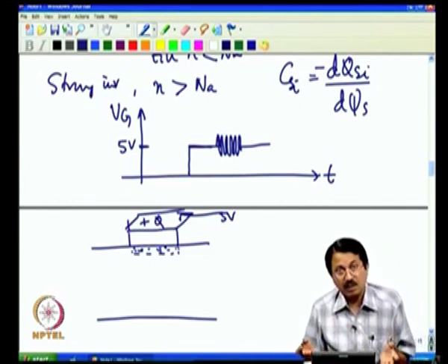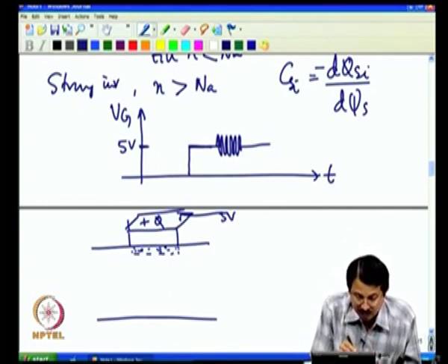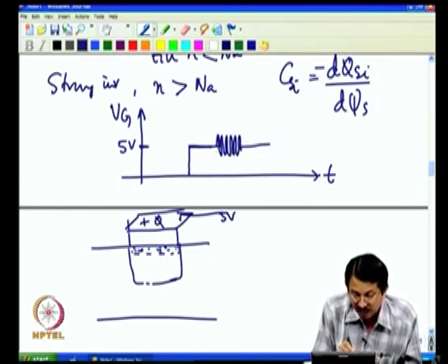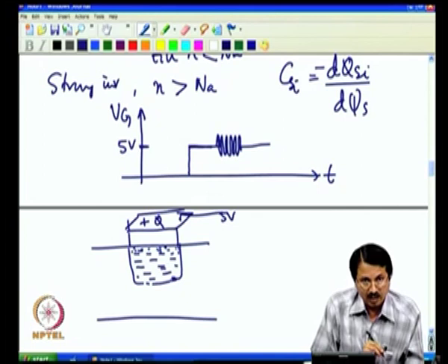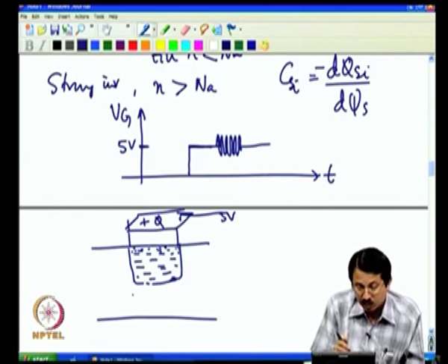The charge is not coming from the electrons because electrons are not there. So, what happens? What happens is very simple. What you really have in inversion condition is a large number of electrons and a large number of acceptors, may not be as large, there are acceptor impurities. So, if this instantaneous positive charge at very high frequency has to be balanced by an equal negative charge, that can happen only by uncovering more acceptor impurities at the edge of the depletion region.